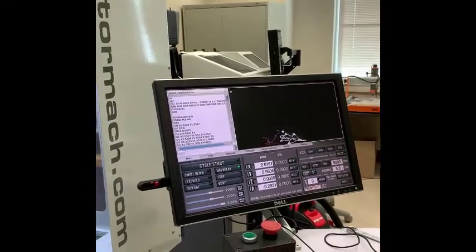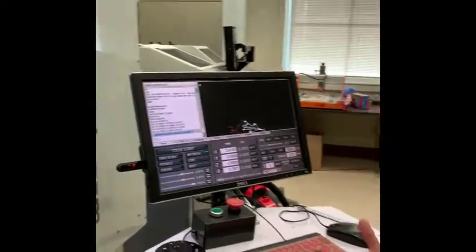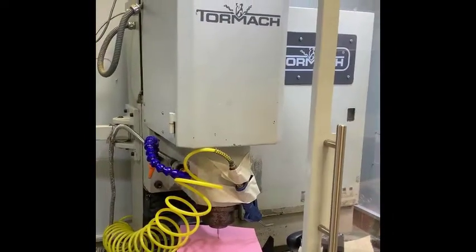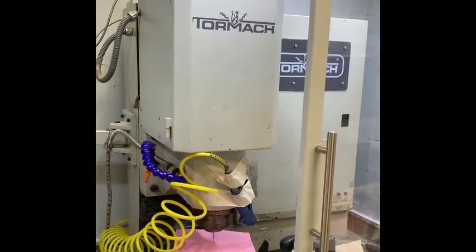All right. So now our Z axis is zeroed, but we still have a small gap because of the thickness of the paper. So we pull the paper out, right? First, we need to bring the tool back up. So page up. Just go to continuous. Okay.